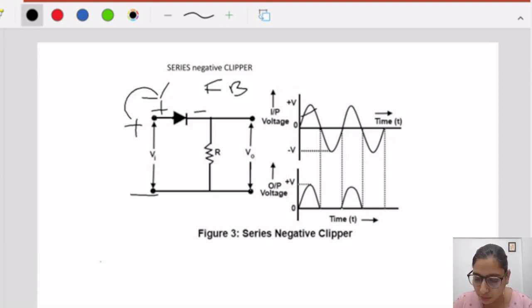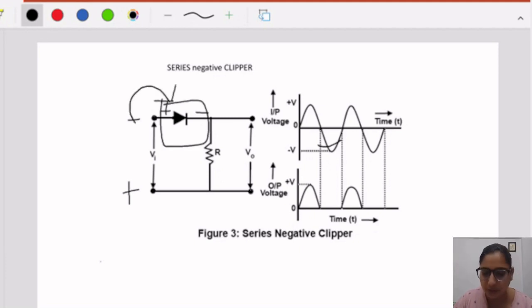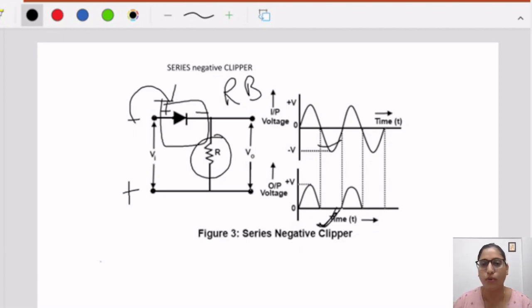If the diode is in forward bias condition, it will allow conduction, and across the resistor we have some voltage here. So this is the voltage. And what happens when we reverse the polarity, or consider the case of the negative half cycle? The polarity will change. Then the diode works in blocking or reverse bias because the negative terminal is connected to the positive of the diode. So the diode is in reverse bias condition. If the diode is in reverse bias, that means no current across this resistor and no voltage at the output.